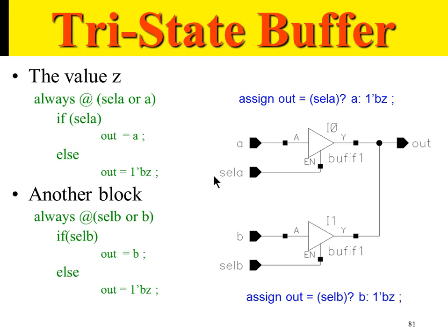So until now, you have seen a port can be declared as an input port or an output port. But you can also declare a port as an in-out port, which is a bidirectional port. In such cases, tri-state buffers come in very handy, where you can control the direction. You tri-state one direction or block one direction of the port temporarily till the other direction is active. So without declaring two separate ports, input and output, using the same port, I can tri-state one direction.